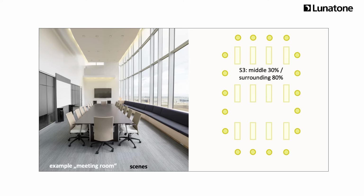Scenes can be created as desired and do not have to follow the DALI groups, as you can see here in scene 4. 2 rows that we did not define as groups are turned off, 6 spots are set to light level 30, and the remaining to 100%. Scene 5 is designed for a presentation setting, where the luminaires are gradually getting brighter towards the rear.